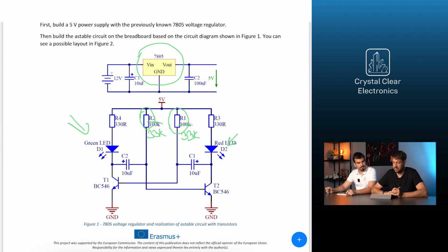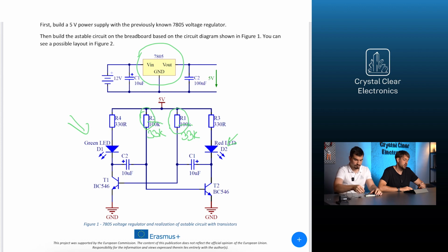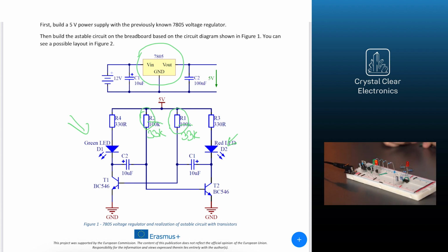If you replace both resistors with 33 kilo-ohms, then the blinking will be symmetrical again, but it will be about 3 times as fast as it was with the 100 kilo-ohm resistor. From this, we can draw a conclusion that the blinking frequency is related to the value of R1 and R2. It's really blinking faster. Now let's continue experimenting.